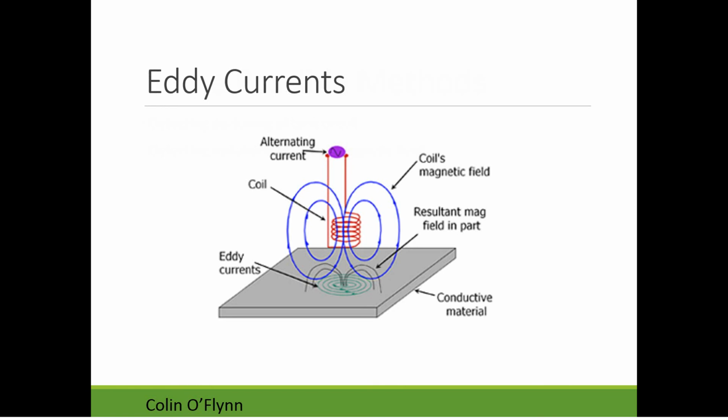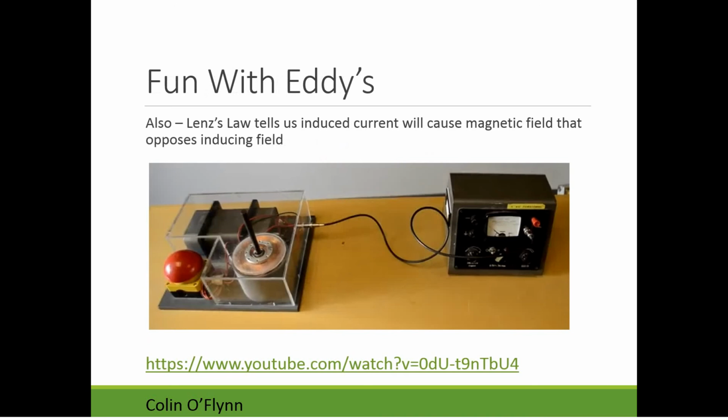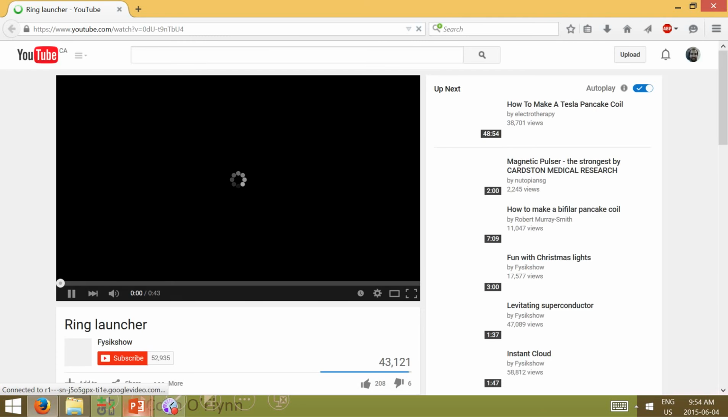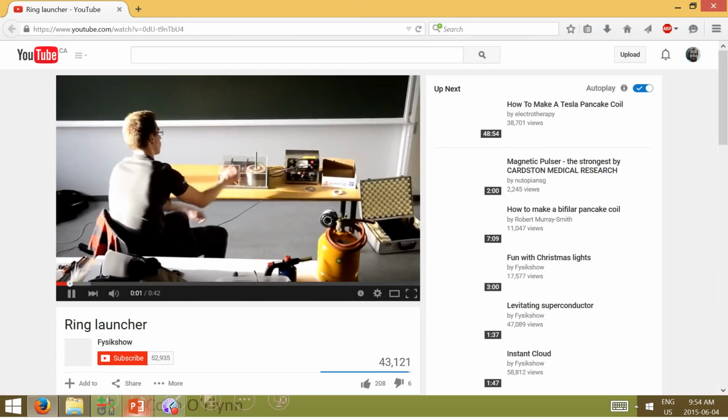How the detuning method works is that if you bring a coil near a conductive metal, a bunch of eddy currents are generated within that metal. These eddy currents generate their own magnetic field that in fact opposes the incoming magnetic field. There's an interesting effect. I'll just show you this before wrapping it up. The field, of course, opposes what the field is that excited it.